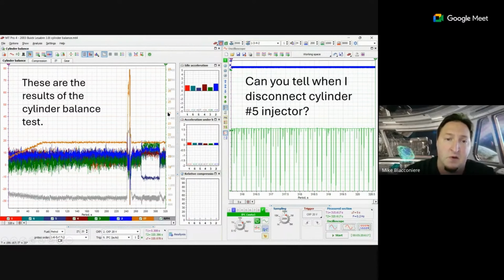I did a bunch of playing around with this to find out how inaccurate I can make it, and it's pretty hard to fool. So as long as you set everything up right, this is awesome for, say, early OBD2 vehicles that don't have misfire monitors, or if you think a misfire monitor might be lying to you. This is a quick, easy test to prove that the cylinder you think is misfiring is actually misfiring.